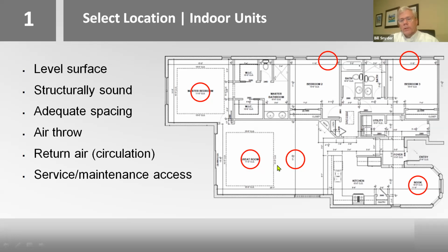But this is a long distance, so you probably only blow about halfway across the room and maybe not hit over here. Maybe you put a couple units on this wall blowing this way. So you just have to consider that. And then when you consider it, where are you going to run your line sets? If you're on this wall, you can come out the outside wall, maybe put a condensing unit like right here. These 2 units would go towards that condensing unit multi-zone, and this unit would go to that multi-zone.